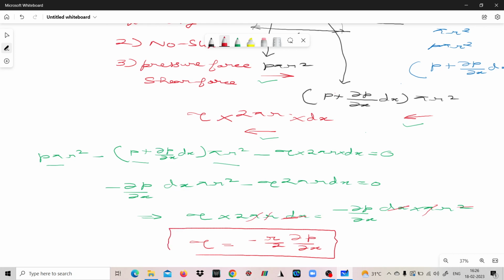So this is the expression for shear stress. Now here, for a pipe flow, the pressure gradient along the flow direction, that is del p by del x, is a constant. This can be proved from the Navier-Stokes equation after suitable assumptions which are relevant to viscous and laminar flow through a pipe. Okay, viscous flow through a pipe. Del p by del x is a constant.